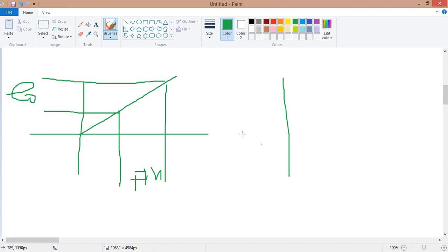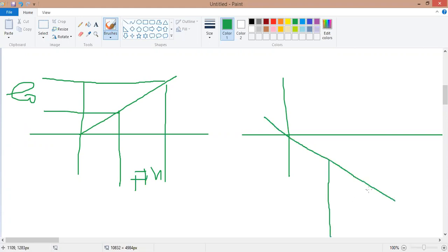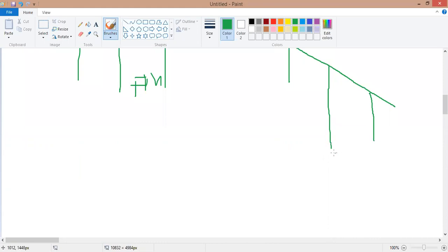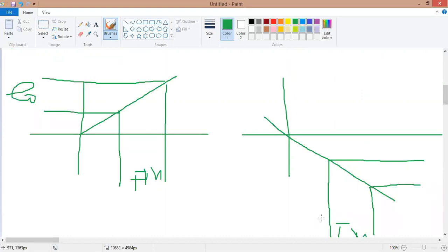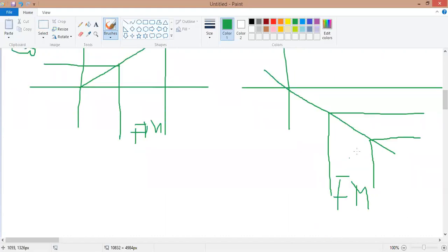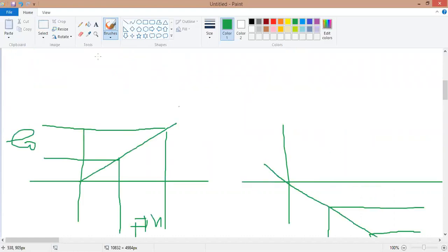And when this slope is decreasing, and I'm applying my frequency modulated signal towards this portion, I'm getting my amplitude from this one, that is negative slope circuitry. Where it is increasing, there is just a 180 degree shift over there. And that is the most important thing.